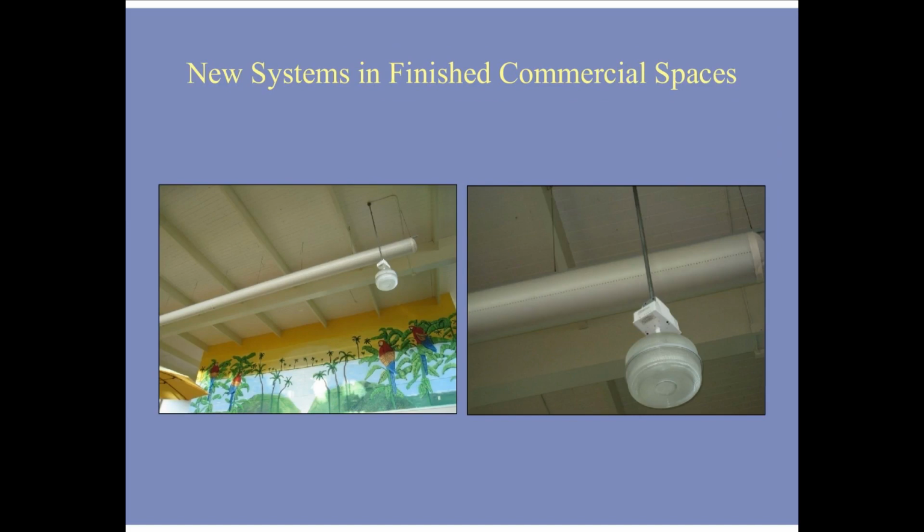While these examples are not in a historic building, this solution may be appropriate in rehabilitation projects. The ducts shown here are an inflatable material that expands when the air is on, similar to a windsock. Rather than installing registers at designated locations, there are small perforations along the side of the duct that allow the conditioned air to escape. The impact on this space is minimal and the duct blends in well with the ceiling.